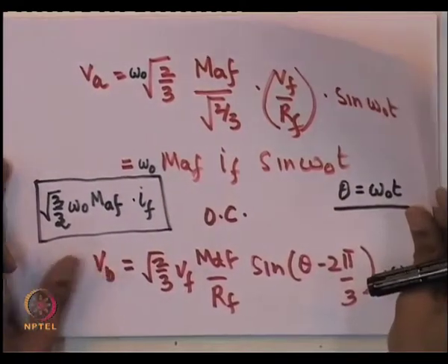The second and more interesting inference about the steady state behavior of a machine was that if a machine was connected to a 3-phase balanced voltage source and we studied a particular situation in which the rotor is aligned at an angle delta at the time when the voltage source to which the synchronous machine is connected undergoes a negative to positive 0 crossing.